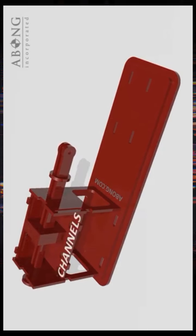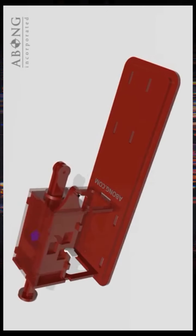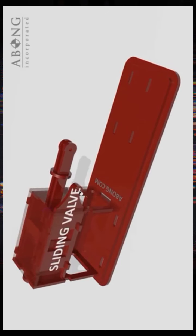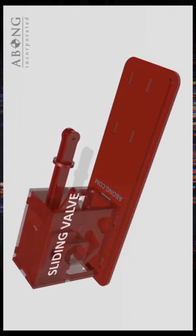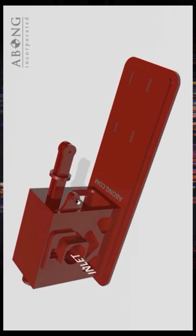To do this, you create a channel connecting each side of the chamber to a supply of steam. Then you supply high-pressure steam first to one side of the chamber, then the other, forcing the piston to move from one end to the other. A sliding valve controls which side of the piston is connected to the high-pressure steam and connects the other side to the exhaust. As long as there's a supply of pressurized steam at the inlet, the piston will continue to move back and forth.